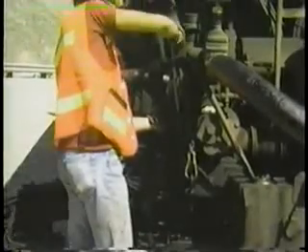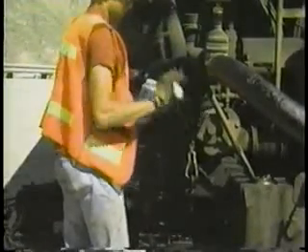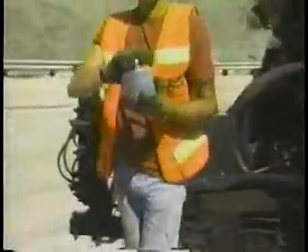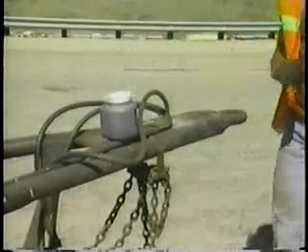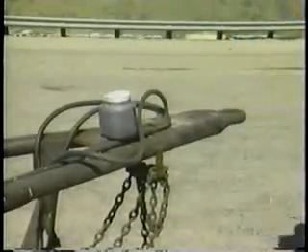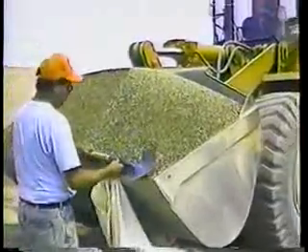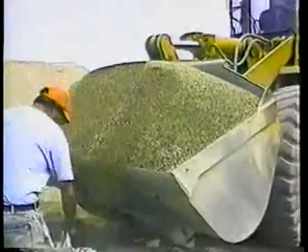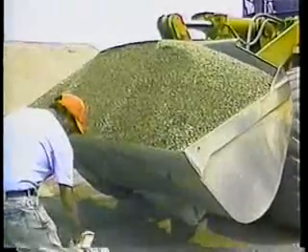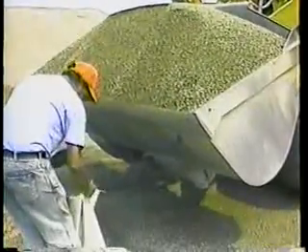Many agencies require that the binder be provided from an approved source. Some agencies may further request samples and specify the type of binder to be used. Be sure to follow your agency's requirements. Be sure the chips to be used meet your agency's specs. The size and type of aggregate depends on the number of applications to be made and the type of binder to be used.